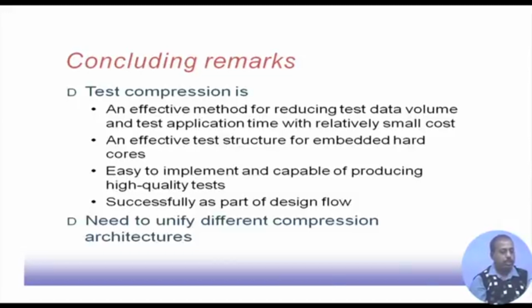By response compaction we can combine the responses into one or two signatures, and that way the amount of information to be stored for the response will also be less. So, we can do the comparison part easily. Now, it is easy to implement and capable of producing high quality tests.